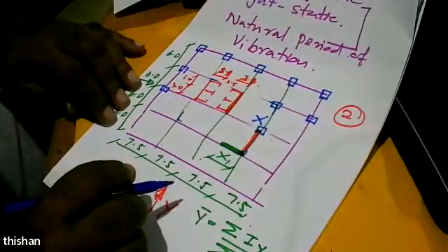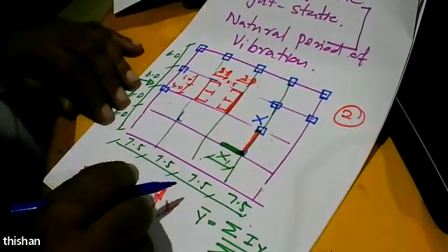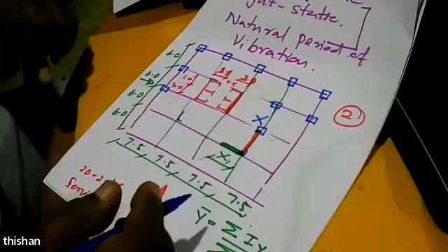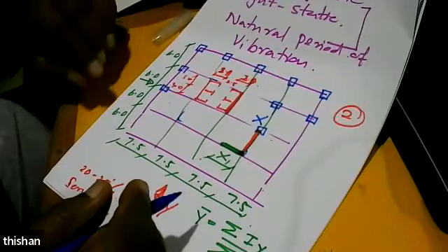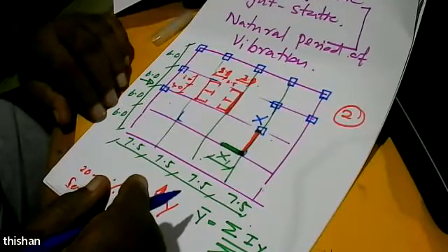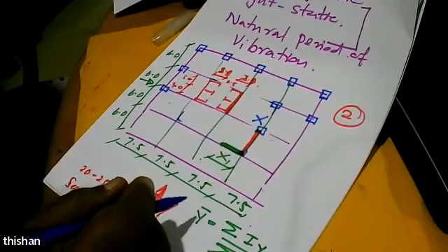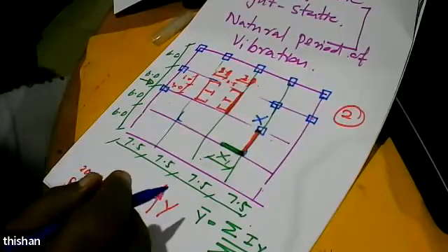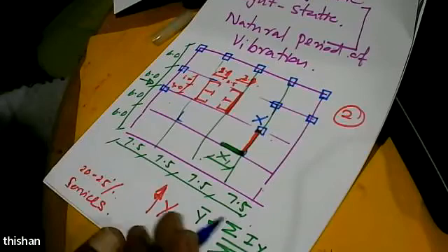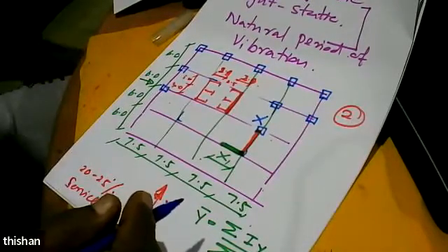Why? We have a wall. But on the other hand, if you think the wall is only 300 millimeter thick, and we are having beams of 400. Then you might ask, okay, would I have a column of 400 by 400 there as the corner stiffening member? I say yes, if you want to have it. And if I'm having it, I'll have 500 by 500. The reason is, if I'm having a wall of 300,